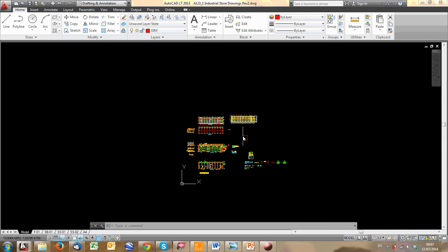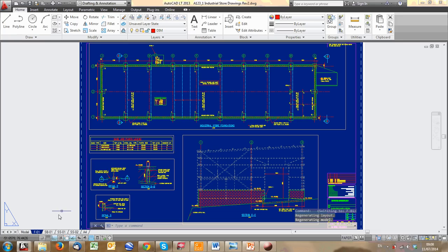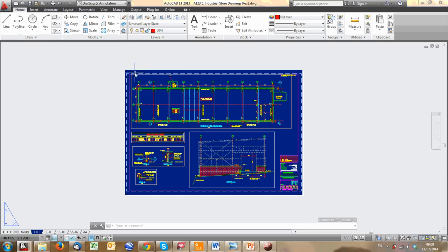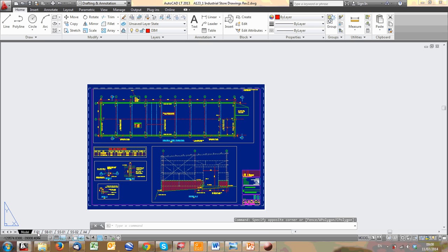Though this is model space, as I said, it goes off in every direction for infinity. But if you want to look into the space and create a drawing, which you can print or PDF or whatever you want to do with it, you need to go into paper space. These tabs are for paper space, and I've set it up that this is the name of the drawing. It's Foundation F01, my first foundation drawing, and this is now a piece of paper. You're looking at an A1 drawing with windows into model space. So from model, you set up a window around, so I will see what's in that box right now, but you create those windows from paper space.